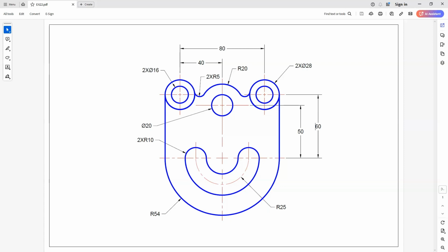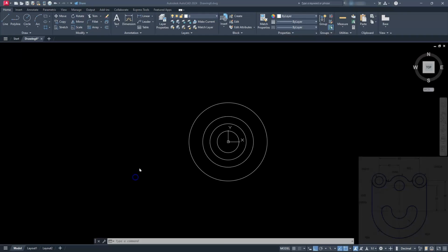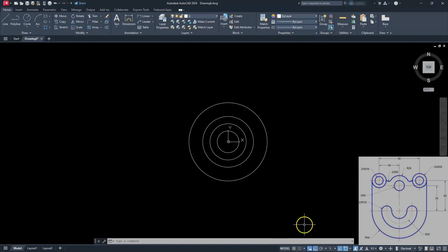So basically what I'm showing you here is that I do have a radius of 25, which is here. Now in order to get this circle, this one here has a measurement of 25 plus whatever the radius is, and the radius of this circle here that's going around this has a radius of 10. So therefore I added 10 to this. That gave me the 35 to reach this one, and to do the inside one I'll have to subtract 10 away. So if I subtract 10 from this, that will give me my 15, and that's going to locate this circle here for me. Okay, so now that we have that created, let's go ahead and turn our dynamic input back on.